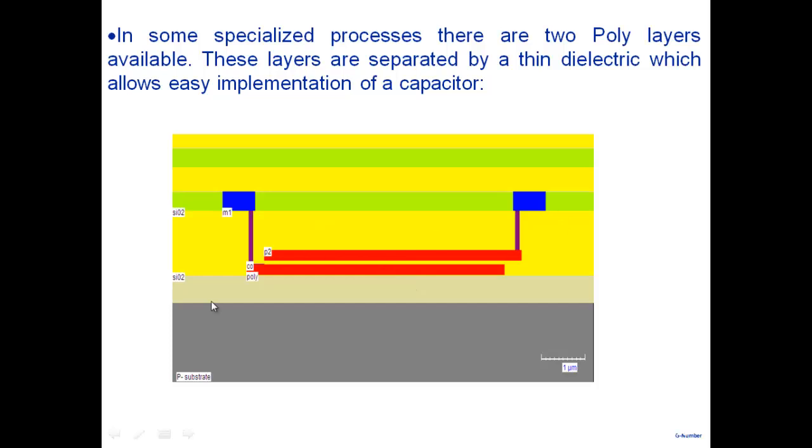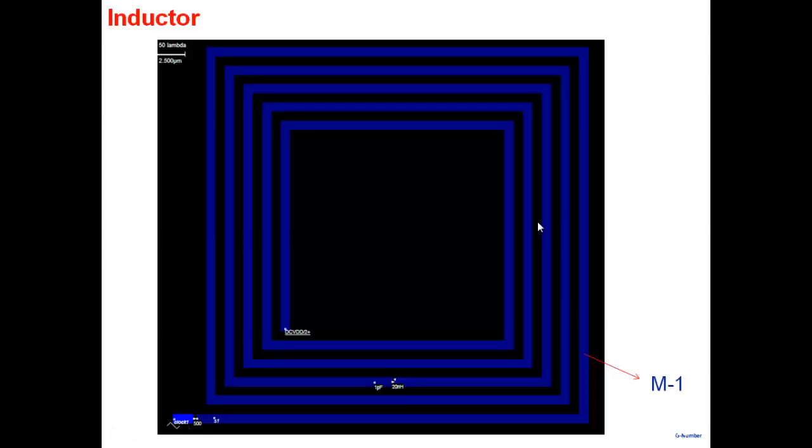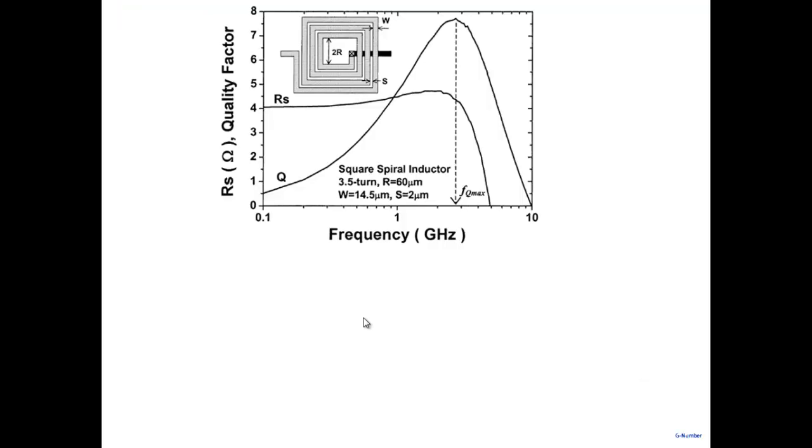And then you make the capacitor, let's say. Well, inductor. For an inductor, all you need is a spiral, right? So we have a metal layer, and all that you do is make a spiral, right? And you get an inductance. So I can use this. So let me show you. You can make inductance, but you don't have an iron core and things like that, so you don't get large values here. The problem with the inductor is that its Q factor is pretty low.